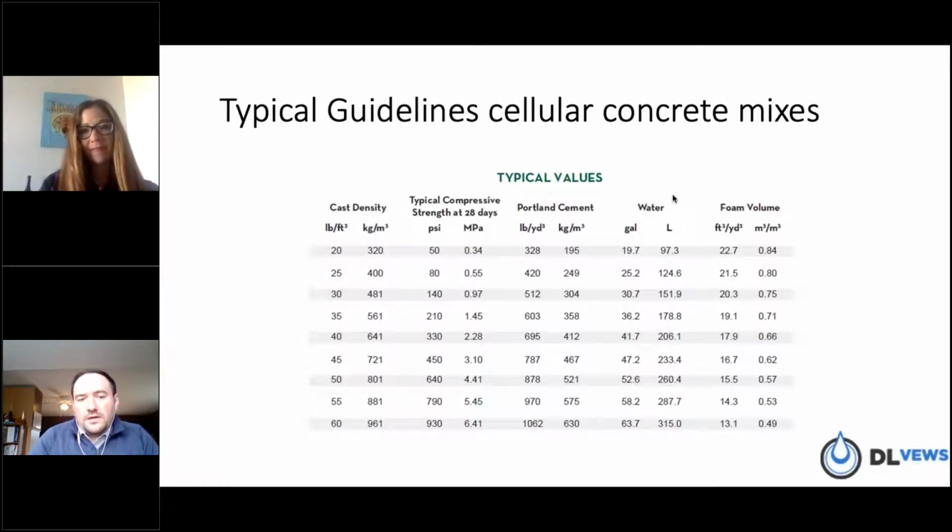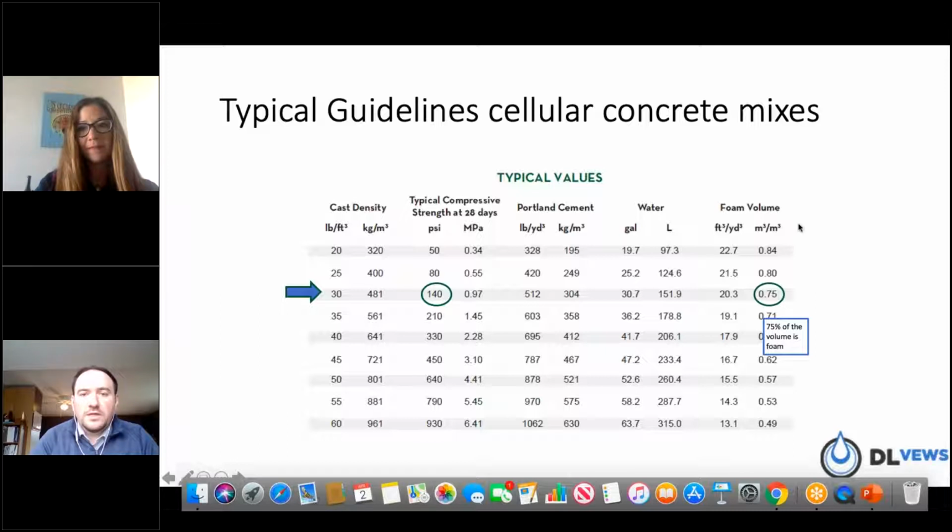So you can see here that this is our normal chart for cellular concrete. And average compressive strengths are usually very high compared to traditionally well-compacted backfill. So when it comes to filling voids behind host pipe walls, like when we talk about lining your average corrugated metal pipe, what have you, or anything with a void behind it, right, with retaining wall, bridge abutment, so on and so forth, the ability to pump this material is very high because it's such a lightweight mix.